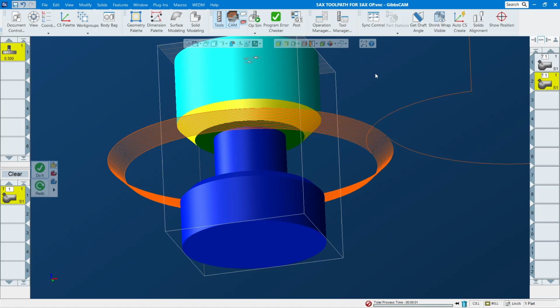Sometimes, with some complicated parts, the surface is not there for you to select, so you might have to extract the geometry out, and then it works better in that case. But like I say, map between 2 curves, map between 2 surfaces, it's very handy, and it works very well for me. I think I've done something like this a while back.